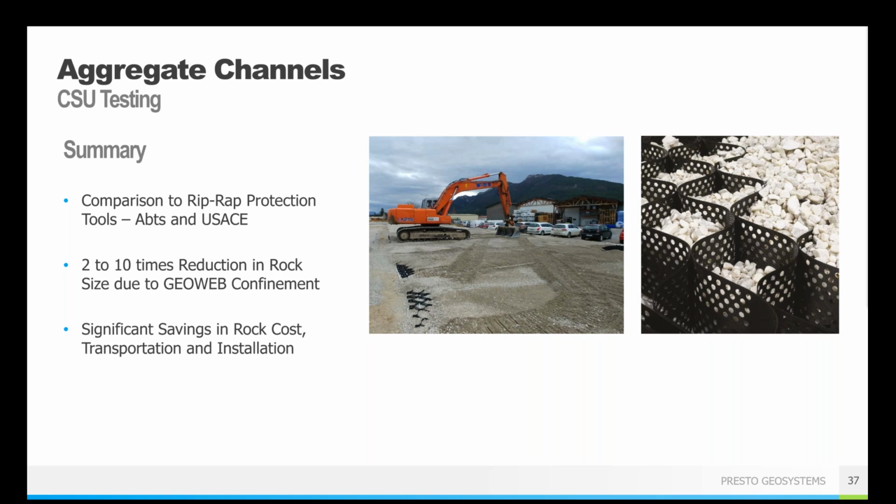We do have our calculations that help us determine which one is going to be the most appropriate based on those project conditions. But yeah, 3/4 inch to 2-inch is going to be the most common sizes of crushed aggregate that we would recommend in that system. So something to keep in mind, there is no one right answer. Again, everything about this is unique to each individual project, but that's sort of the range that you're going to be looking in.